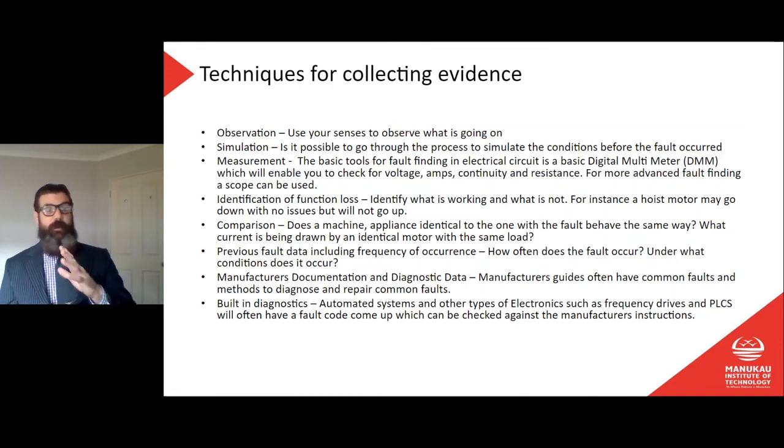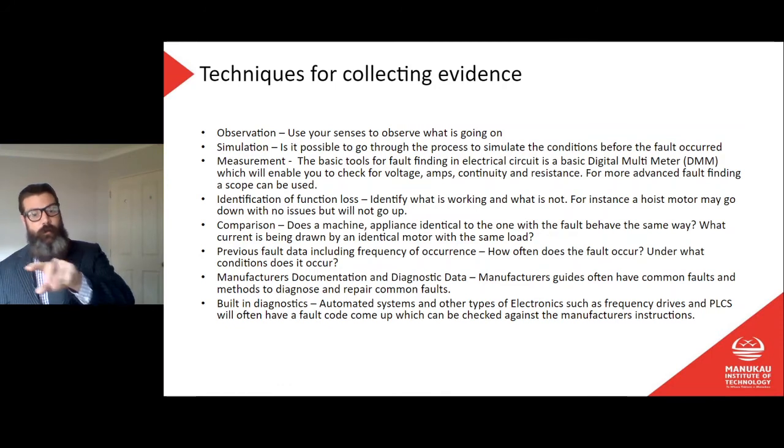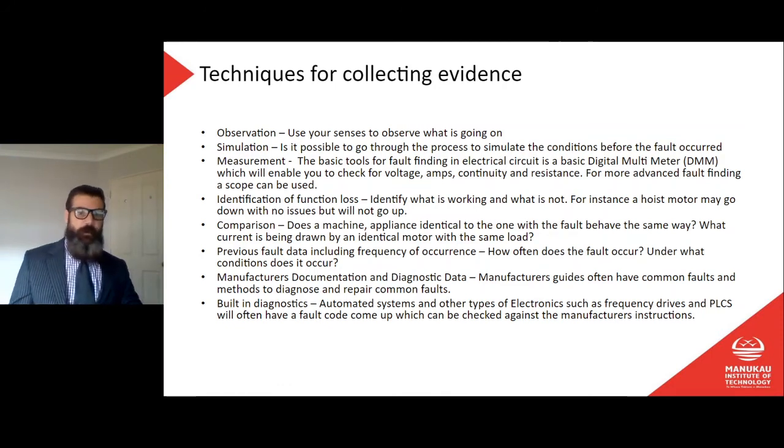I tell people, 90% of fault finding actually is voltage in, voltage out. Is there voltage into this thing? Yes. Okay. Is there voltage out of this thing? No. All right, that is the thing that is broken.